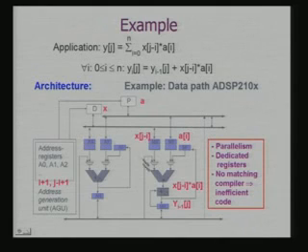And the architecture typically supports various registers. So, for example, here I have got a_i, I have got x_(j-i), and they will be computed and we shall get y_(i-1), which has to be used for the subsequent steps as well. So, how to use these registers optimally, that becomes a basic problem. And you also have automatic address generation units.